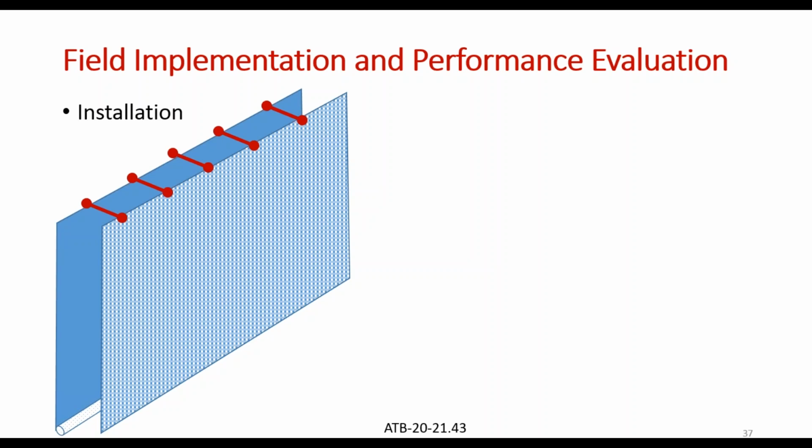After this, you need to place your first layer of porous backfill, and then you can be more ambitious. You can place another layer, but you cannot place more, because it has weight and a tendency to push the fabric away from the wall.